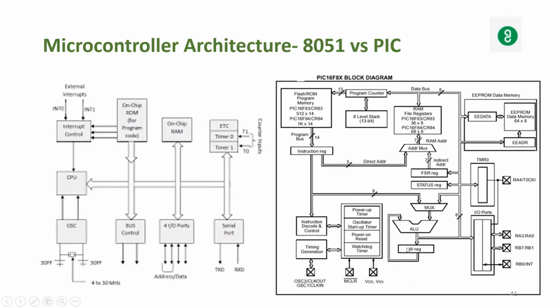It takes W register help. Repeated computation, it does with the W register. And once the output is obtained, it passes to the input-output ports through this bus. So whatever is in the ALU, you can very well see the status of the ALU using the status register.